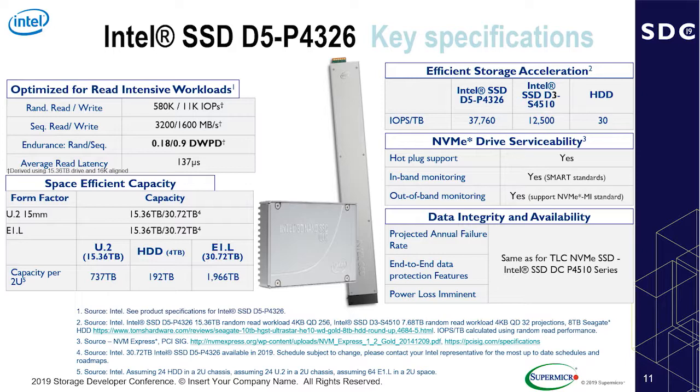Because then what happens, let me just explain this, you end up doing a read modify write. It's still going to do a 16K block. So it's going to read that 16K block. Let's say you're doing a 4K write. It'll plug in that 4K, do a read modify, and then write it again. So if I do that 4 times to do 16K, that hits my endurance 4 times, and it also hits your performance, because you're doing this read modify write slowness. So just don't go there.